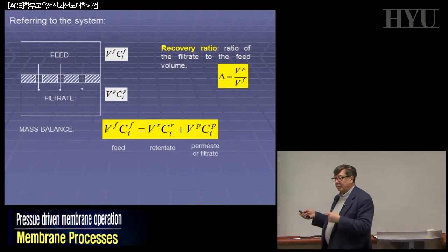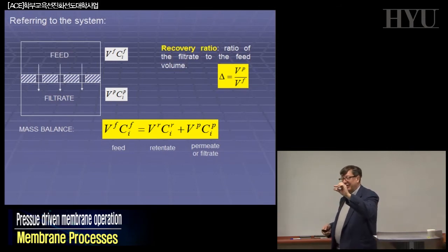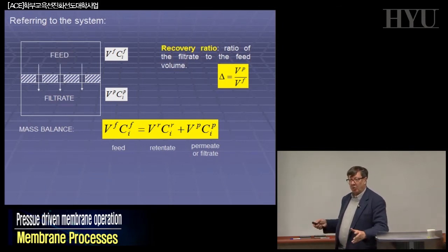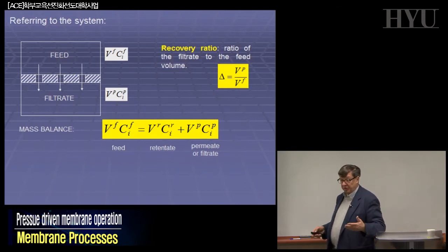With reverse osmosis, we will see you can operate with 50–60%, and now you understand why, because if we increase too much, the osmotic pressure increases too much, and the pressure you have to apply becomes 300 atmospheres, etc. No way, everything is too expensive, it needs stainless steel tubes of 2 centimeters, etc. But up to a certain value it can be done. And so we work now with about 50%. That means if you have 100 cubic meters, 50 cubic meters will be fresh water, and 50 cubic meters will go back to the sea, which is interesting.